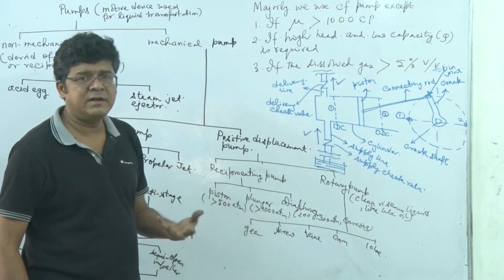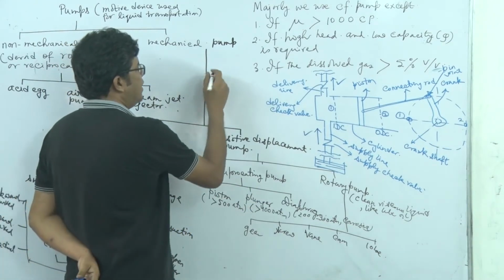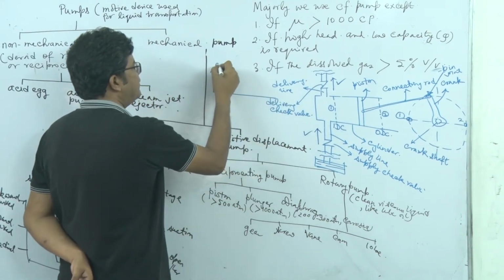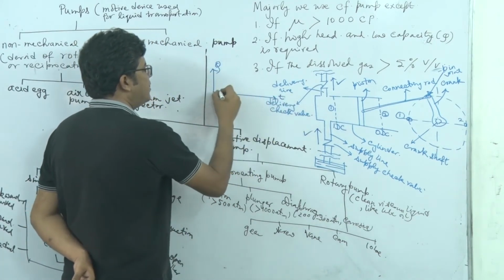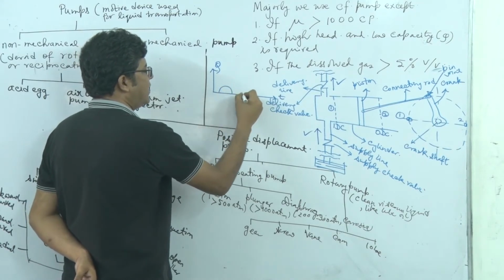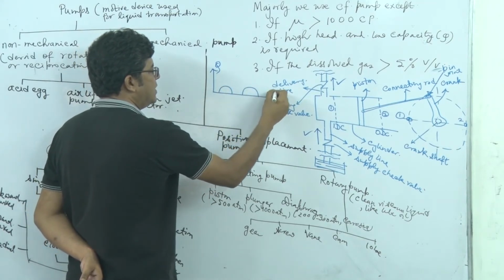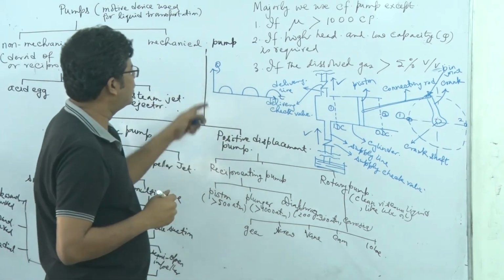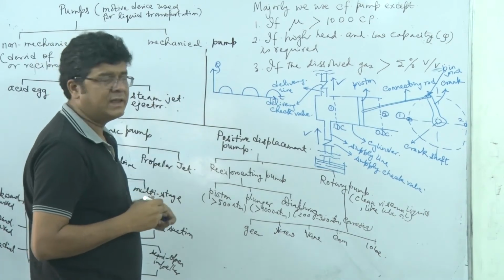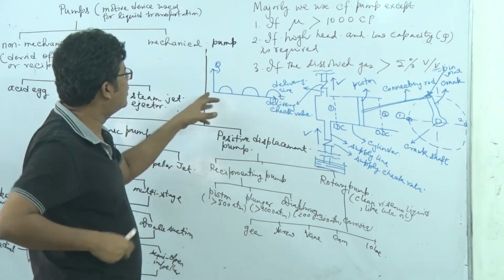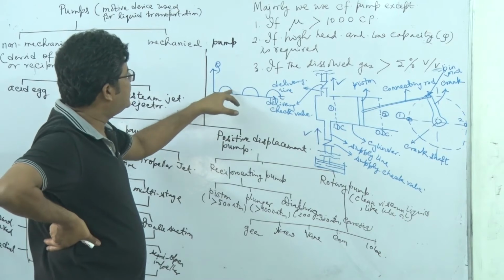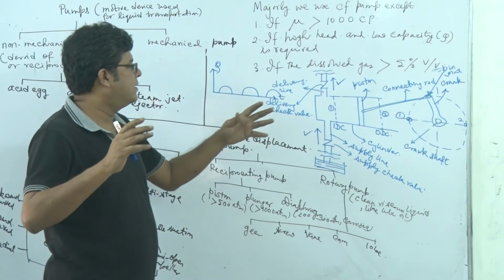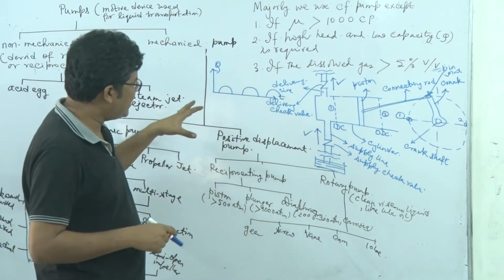Now what is a plunger? And I would like to mention that in a piston pump, if I plot the volume flow rate versus T, it will be just like a half-wave rectifier type plot in a single piston pump. Because over this suction stroke, there is no flow, only over the delivery stroke, the discharge stroke, we will have the flow.